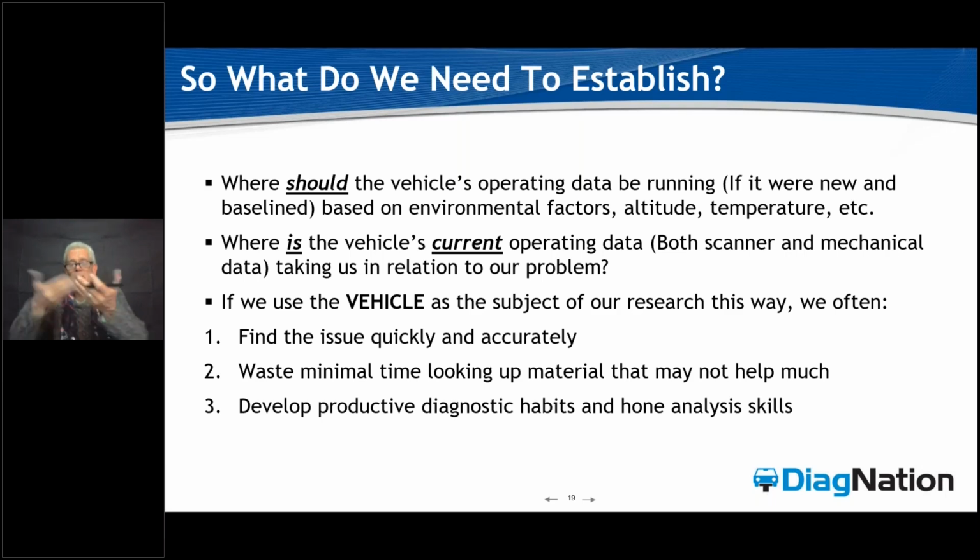What does that mean? Warm the car up before your induction service. You're going to capture the 5 or 6 data PIDs I'm going to leave you with today. And then you're going to just take 5 minutes after the service, which sometimes we have to do anyway because we set a check engine light or something, right? 5 minutes, warmed up after the service, pull the data again. Now we've got an idea of what clean versus dirty looks like. And if we do that over and over using that same data set, man, we have a very powerful diagnostic tool there.